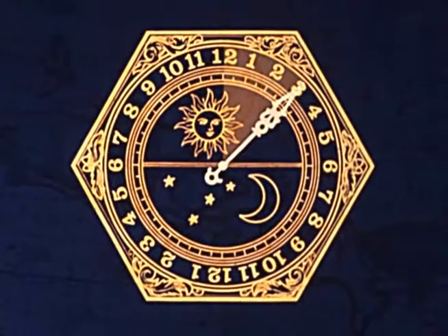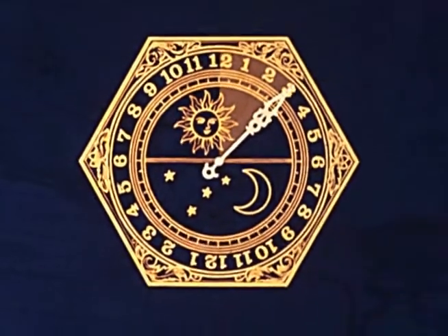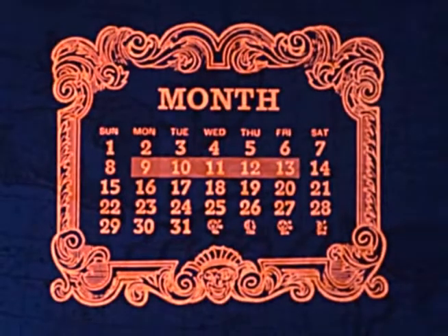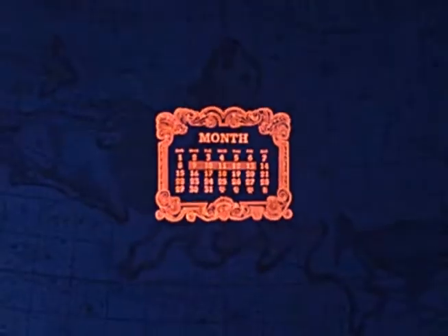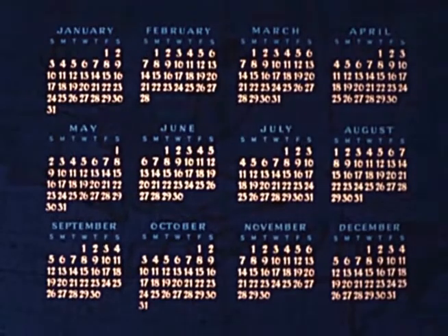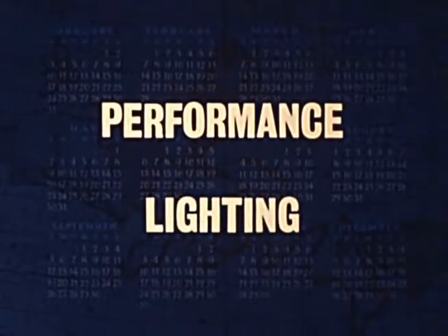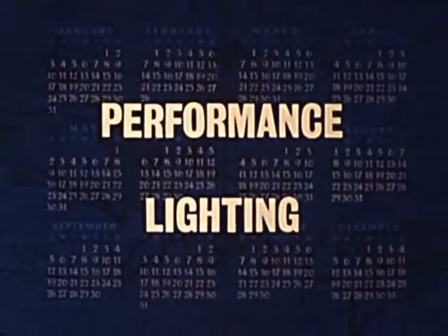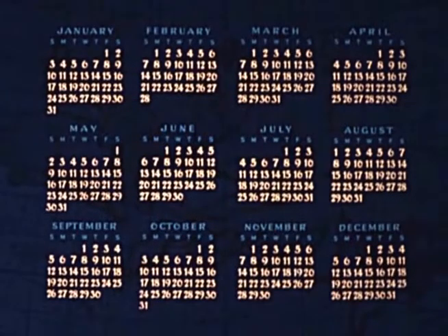We have seen how the daily launch window is developed and the development of the monthly launch window. Now let's look again at the launch windows possible throughout a year. The entire set of constraints may be placed into 2 areas: the performance of the overall space vehicle system and the lighting of the landing site at the time of landing. Let us assume, as we did at the beginning, that only 1 lunar landing site has been selected.